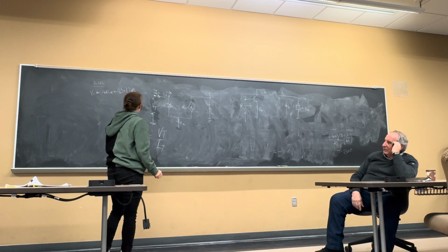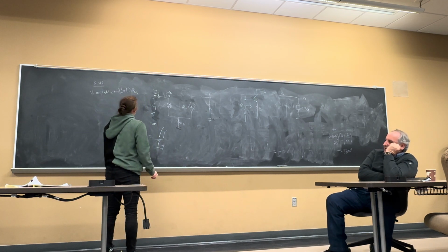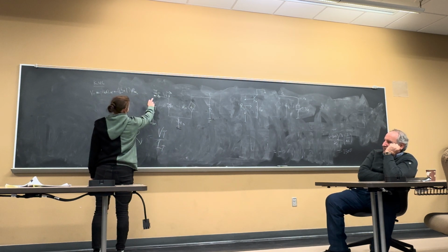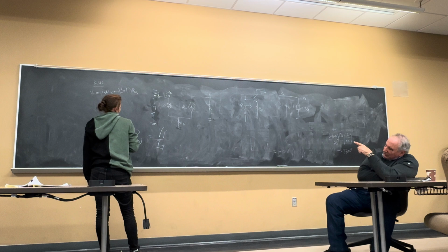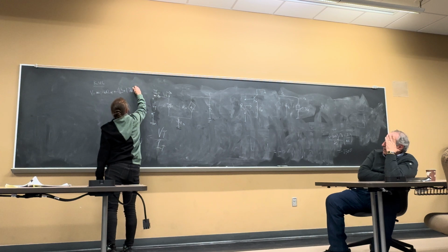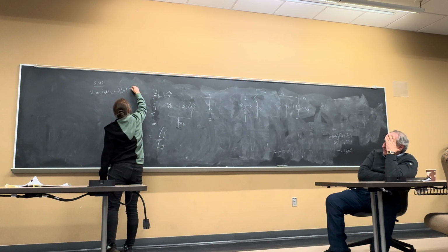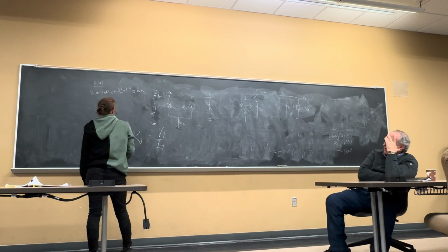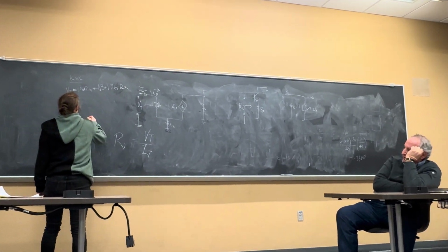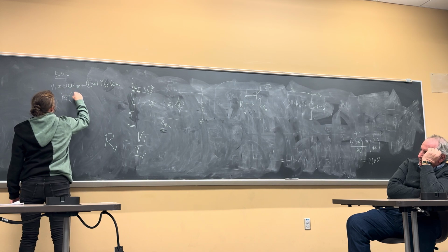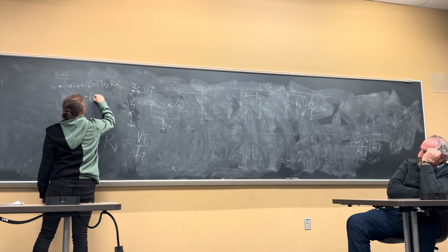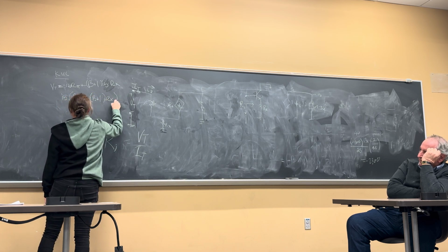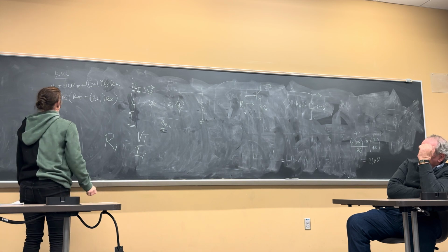I see it. Okay, now what's IT equal to? Equal to IB, correct? So IT equals, okay, now, beta plus 1 IB Rx. You left IB out of the second term. Now factor IB out on the first equation: IB times parentheses R pi plus beta plus 1 Rx, right? Okay, now this is equal to VT.